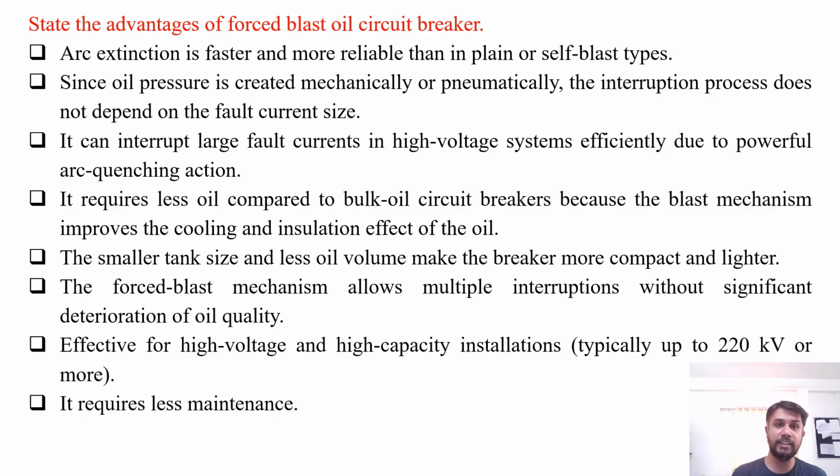State the advantages of forced blast oil circuit breaker. Arc extinction is faster and more reliable than in plain or self-blast types. Second, since oil pressure is created mechanically or pneumatically, the interruption process does not depend on the size or magnitude of the fault current. Now it can interrupt large fault currents in high voltage systems efficiently due to the powerful arc quenching action from the external pressurized force.